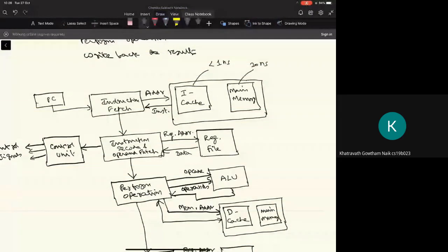So we see that this instruction decode and operand fetch stage does not take any significant amount of time, and that can be completed in less than 1 clock period, even if it involves fetching 2 register operands. And if I have only one read port in the register file, it still takes only the delay of the demultiplexer. That is not significant, as we have seen, because the delay of the demultiplexer is only a few tau, where tau is the propagation delay of a logic gate. So typically this second phase can be completed in less than 1 clock cycle period.